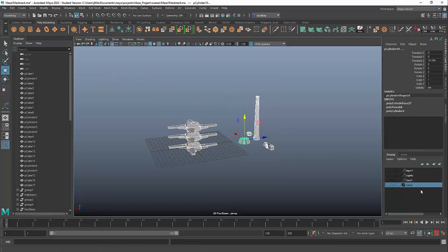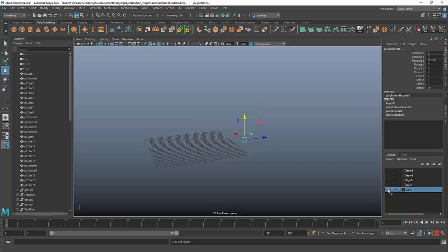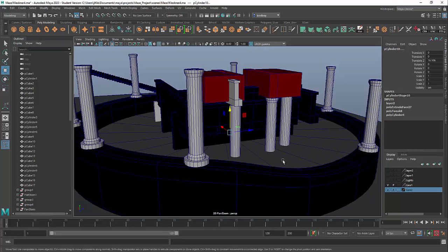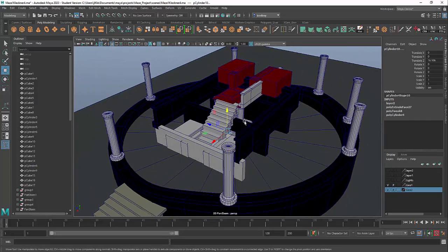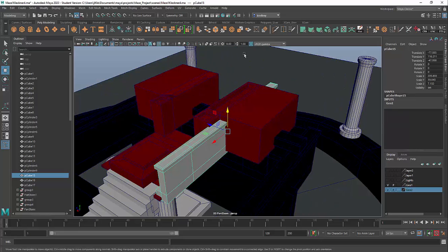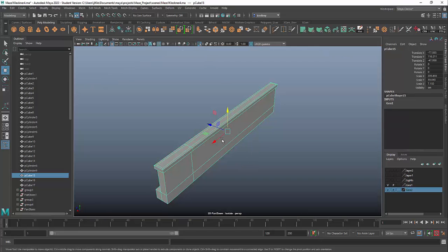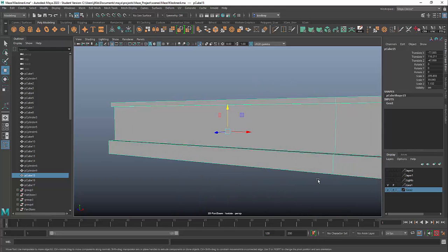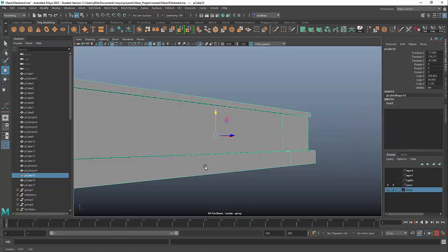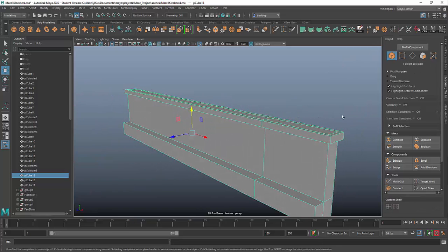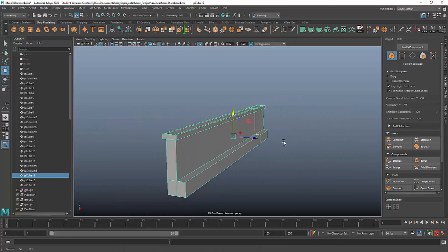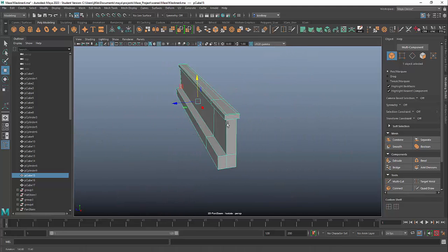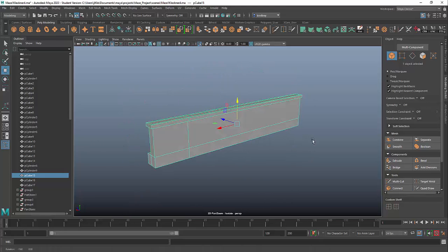Let me set this all on its own layer here. And I'll turn these back on real quick and zoom out. So you can see this wall geometry here, for example. If we frame in on that and then solo it again by clicking on this little icon here, you can see what I've done. You can imagine it as, oh, I used that multi-cut tool to cut away there, if I click on this tool here. So I use this guy. I added a multi-cut here and a cut here, and you can see where I've extruded out some geometry and pulled it out a little bit on the top and the bottom, and essentially created a little wall there.